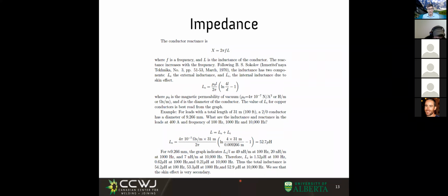And for that reason, if you have a welding process that involves sharp pulses, for example, STT, you want to have short cables. If the cables are too long, you're paying for a machine capable of doing high pulses, but you are not getting the high pulses. You get the worst of both worlds.